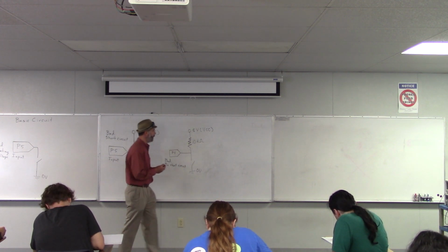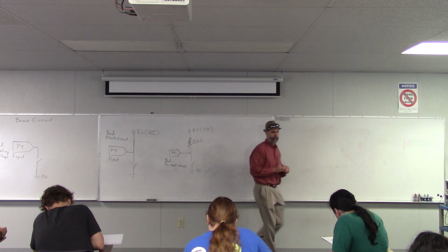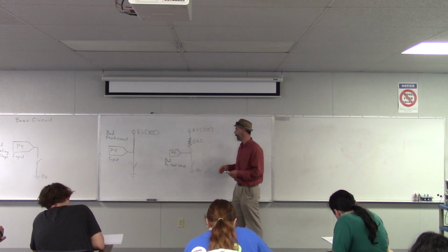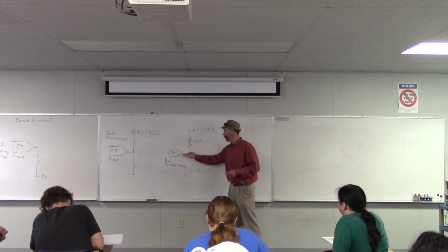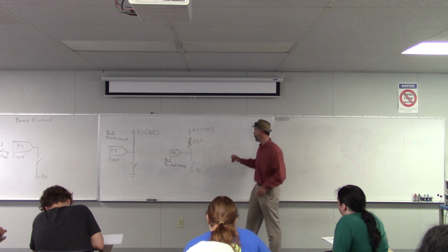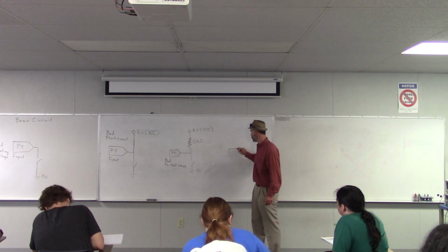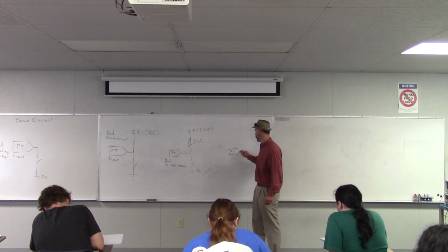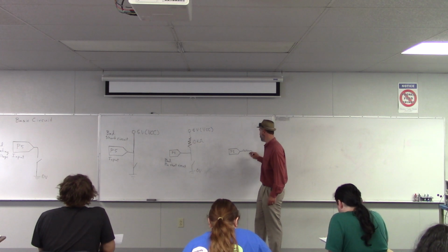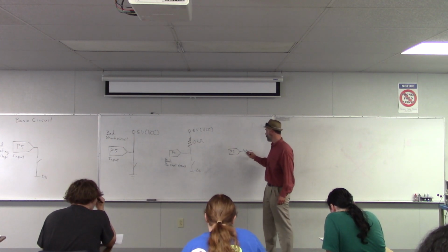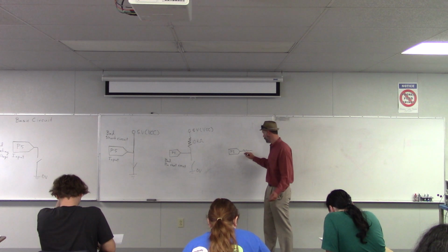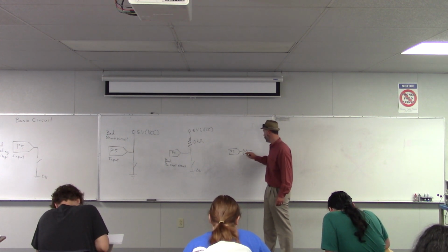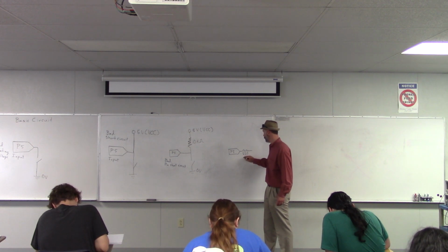So we need to put in one more thing. Just like we use a resistor here to protect the power supply, we can use a resistor here next to the pin to protect the pin. So we still have pin 5. Now we put in a resistor here, and this one can be relatively small. So 220 ohms, I think, is what's used in this case.